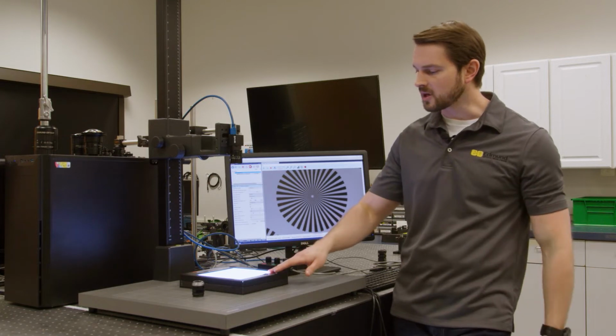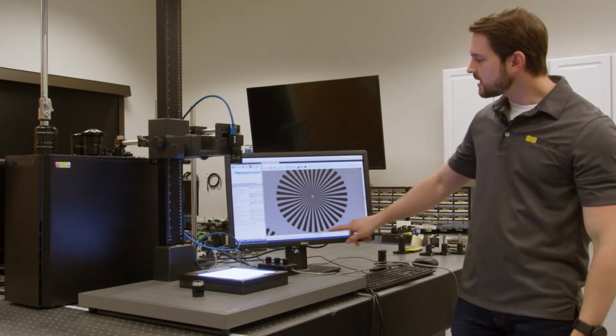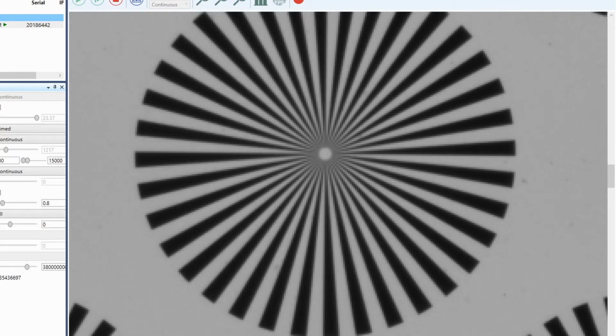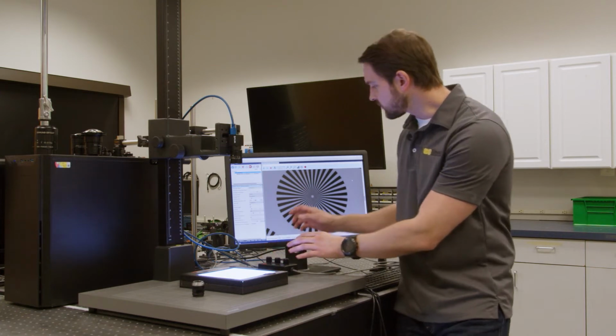Right now I have composite white light going into this lens, and I focused it for the white light in the center. I zoomed in so that we can just see this central star, and I want to take a look at how a lens that's well corrected for this behaves. I'll start by looking at blue, which is our lower wavelength. Our current performance with white light looks pretty good. We're almost all the way bottomed out on this target, and I'm about 300 millimeters away from this glass target. So I'm going to turn off my green and red channels.